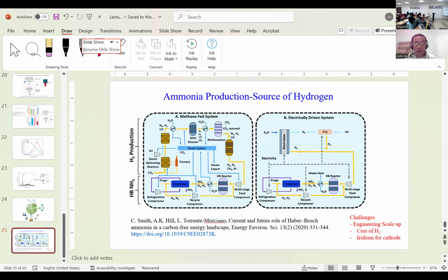If you see, for most of the Haber-Bosch process, we are dealing with the downstream separation. When the ammonia comes out, they have a cryogenic condenser, and then they compress and then recycle. All right, because the single pass conversion of ammonia is not 100%. So you separate ammonia, you have to recycle hydrogen and nitrogen, and then you have to recondense, recompress, and move back. Now this Haber-Bosch